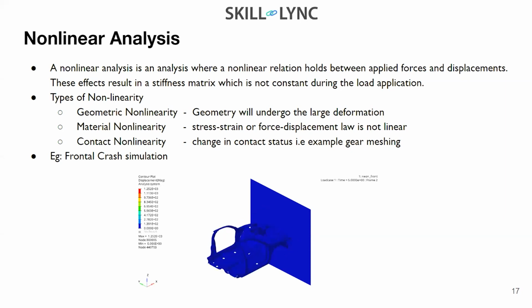So what people have done in research and development in the crashworthiness industries is that they have allowed certain deformity in the BIW outer structure, such that it deforms, and the potential energy of the shape deformation balances the kinetic energy, so that the passenger inside is safer.